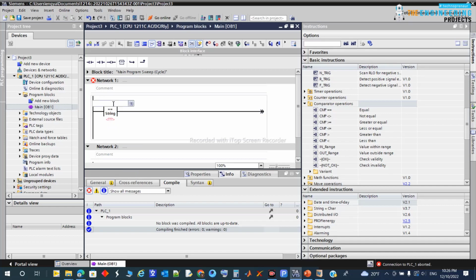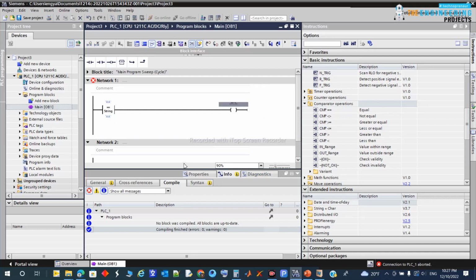Let's put in operand 1. It could be a literal AA, as we saw in the example. It's not allowed, I think. So let's try this one, AA. Yes. And this one, a single quote A also. Then put here one coil. This part is the RLO, and this is the coil of the output. I can see this is output Q 12.7, for example. This is our output to test, and let's download it.